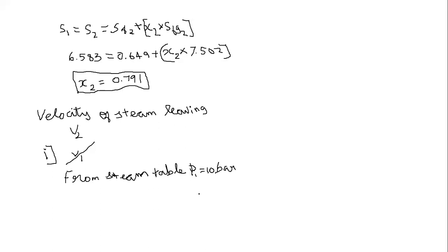As it is a dry saturated steam, the value for H1 is equal to the value of Hg1, which is 2776.2 kilojoule per kilogram.